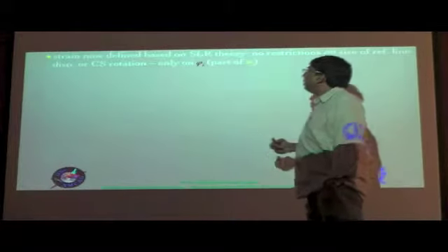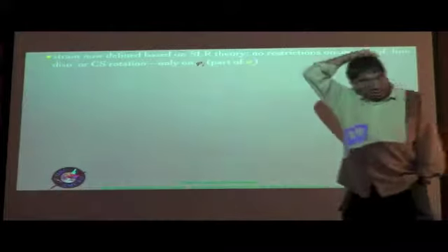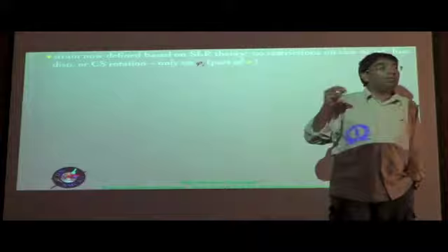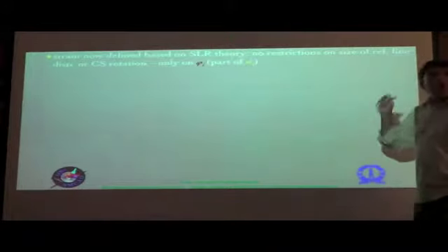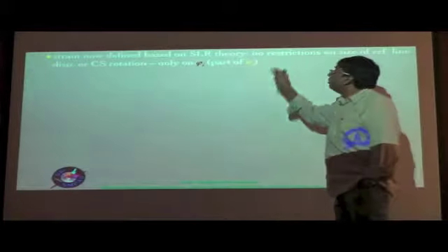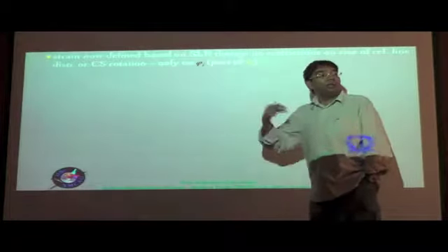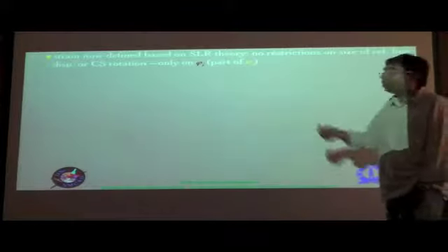Now the strain is defined based on the small local rotation theory. Remember that we are restricting ourselves here to the class R beam, but as I said, there can be some specific loading cases in class T and S beams for which also this might be still applicable. But let's look at this. So there, again, even though we invoke the small local rotation theory, again, as we said, it is something which is a fallout of the small strain itself. Because of the small strain, therefore, the local rotations are small for such cross sections.